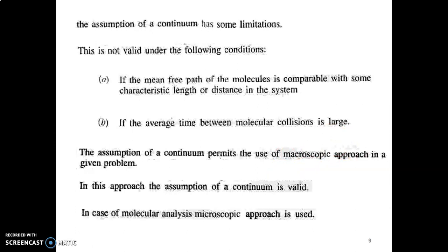And in the case of molecular analysis or molecular dynamics, in the case of atoms and molecules, if the gaps are very large, such that the Knudsen number value is greater than 0.01, we cannot use the continuum concept. In that case, we will use a study called molecular analysis or molecular dynamics. In that case, the microscopic approach is used. So in the microscopic approach, continuum is not valid.